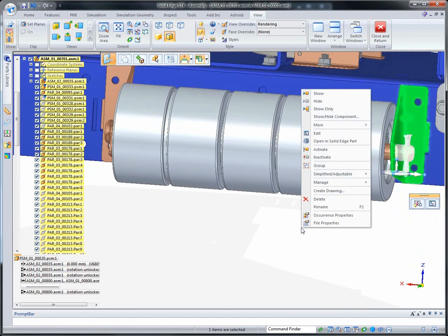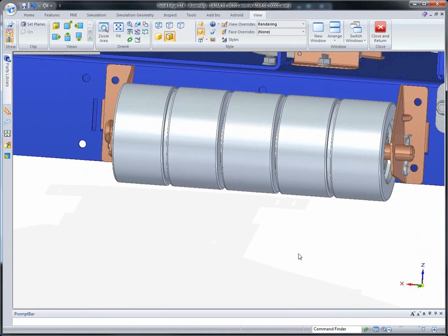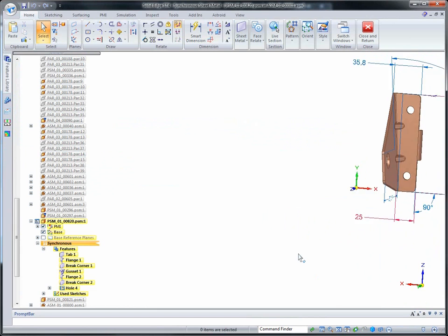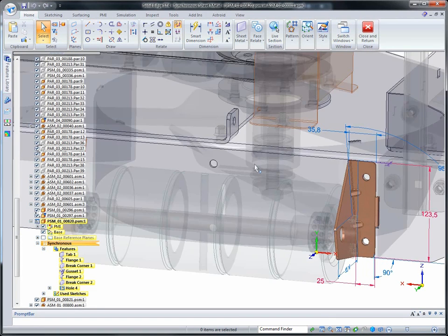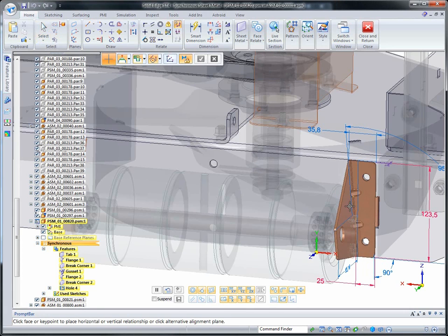This is the advantage of top-down assembly design, in that you can see the changes that you're making, how it's affecting the overall assembly. Next, we're going to add a horizontal vertical lock to the angled bracket. When we select that face, it automatically will snap to vertical.